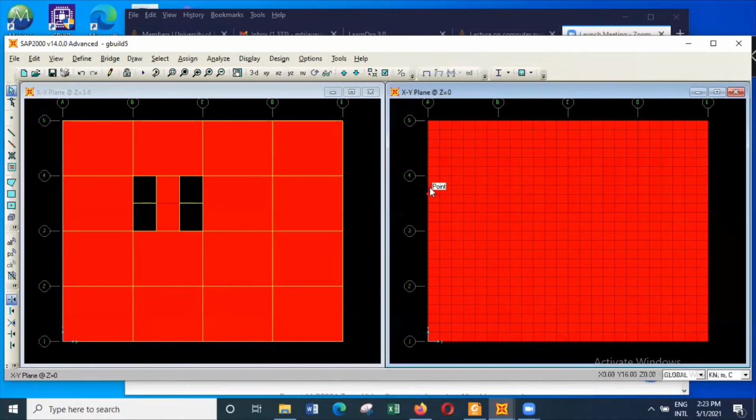So the way I have divided, all these shear walls are now connected. We have another short shear wall this way, and that point is taken as 18.75. Here also you can see 18.75 is here. So basically now the raft has been created so that the nodes of the raft coincide with the nodes of the shear walls, which means the shear walls are properly connected to the raft.